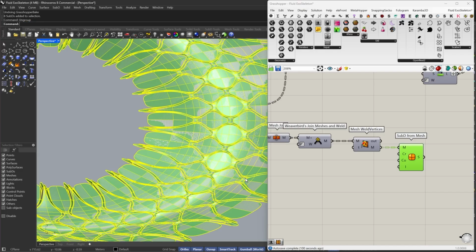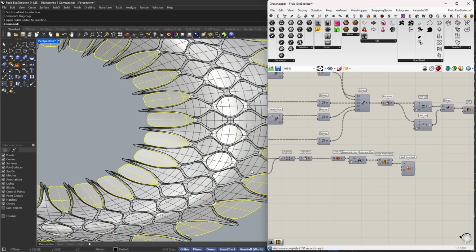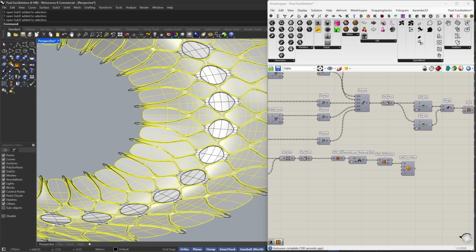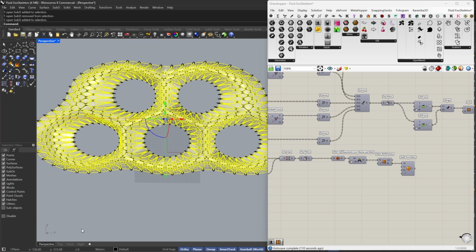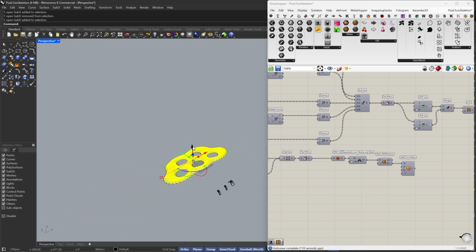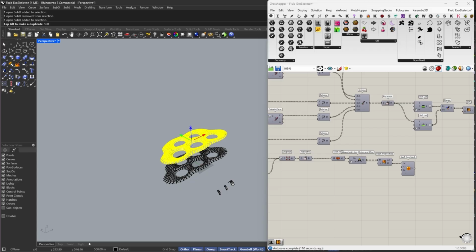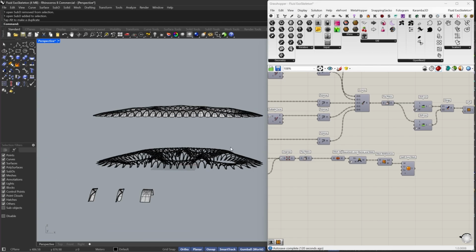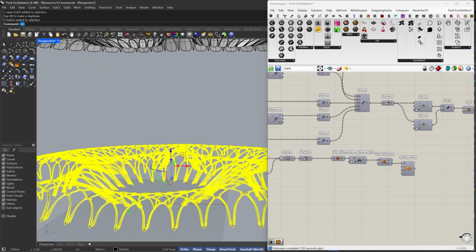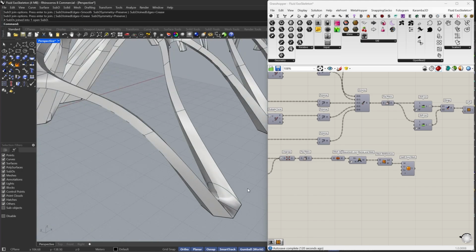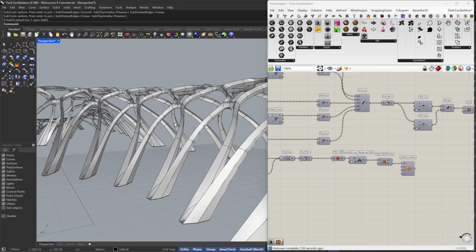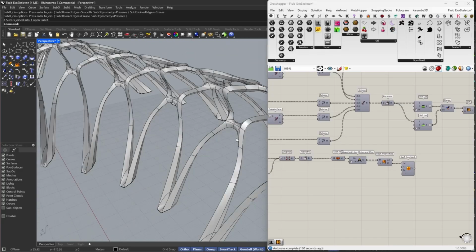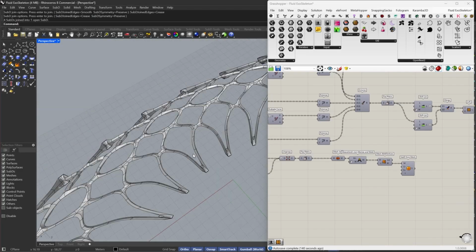Let's ungroup, I shouldn't group, okay. And then right now I'm going to select not this one, I'm going to select this, and let's go to here and move them anyway, so maybe 500 or something. And then I'm going to select all of these and join, but in this case I'm going to crease. And once you do that, you will notice that you gained all the details that you have done in the original mesh, or the original sub-D.